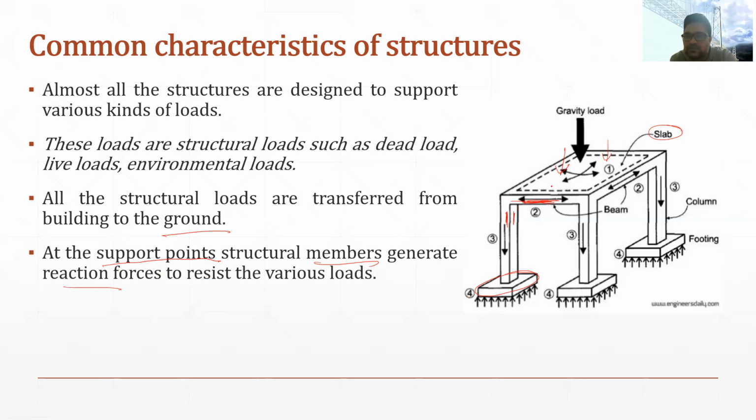For example, the slab is transferring the load on the beam, and the beam is further resting on the column, the vertical member. The point where it is connected, when the beam is transferring the load to the column, will offer a reaction. The beam is having vertical load, and this vertical load is transferred to this vertical column.